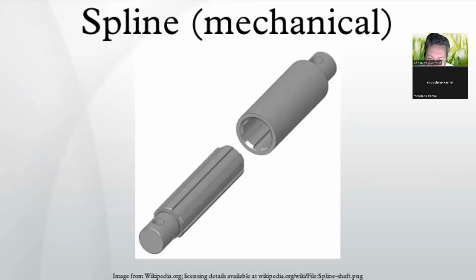Aircraft engines may have a spline upon which mounts the propeller. There may be a master spline which is wider than the others, so that the propeller may go on at only one orientation, to maintain dynamic balance. This arrangement is commonly found in larger engines, whereas smaller engines typically use a pattern of threaded fasteners instead.